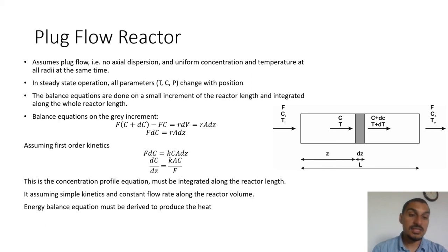In gas phase reactions, you should have one more equation, which is the change of pressure with distance, because the change in composition will result in a change in the partial pressures and will result in a change in total pressure. So this is one more parameter that you should take into account, and one more equation that you should solve with these equations.